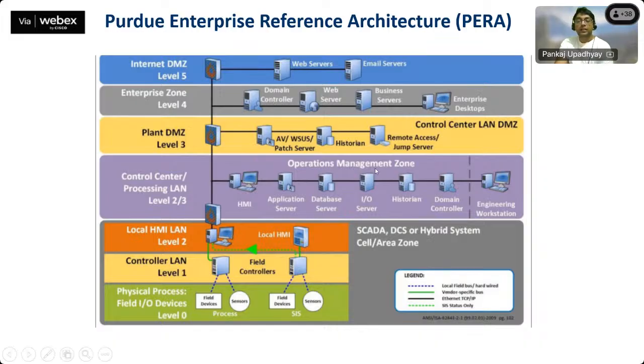So Jagdish, you asked what kind of software and systems we use to protect DCS systems or these OT softwares against cyber threats. The primary and most important step we need to take is network segmentation. If we don't have proper network segmentation, we are keeping our attack surface wide open.